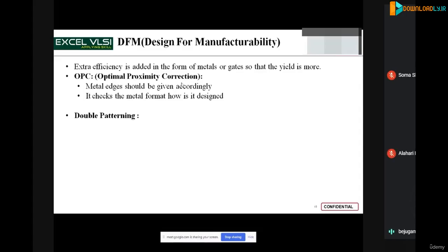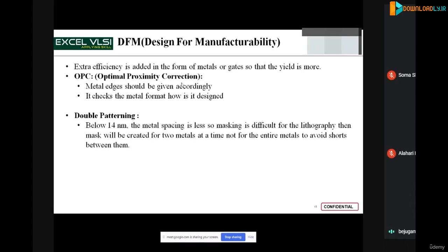Now, next we enter into a stage called design for manufacturability. Once the design is physically implemented, we have done physical verification. We have checked for the metal issues, whether the connectivity is proper or not. Now, can I send it to the manufacturing stage? I should make sure of things here itself, because once it goes to fab, we can't modify whatever has been connected. So we need to check things once the post routing or post physical verification is done.